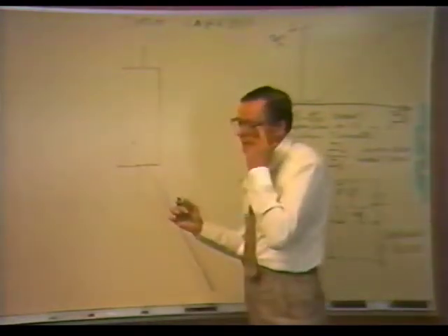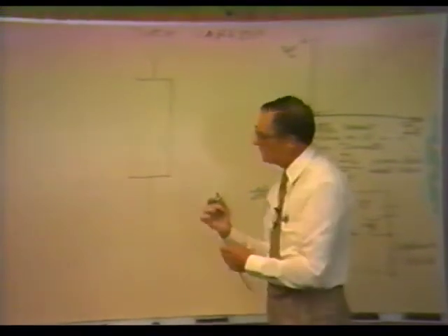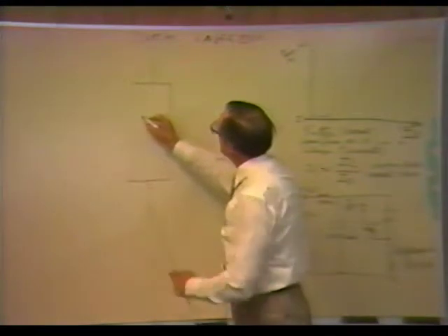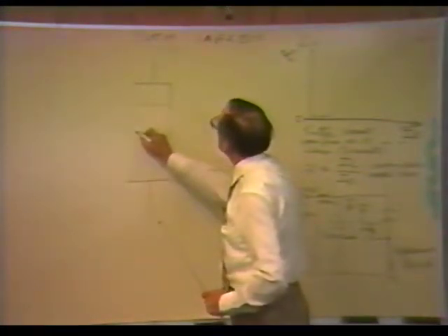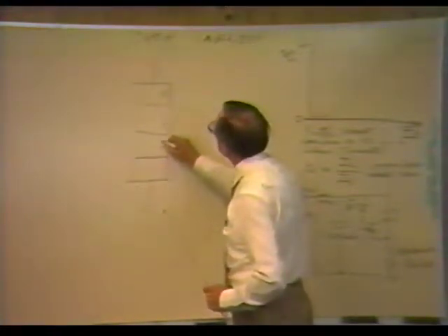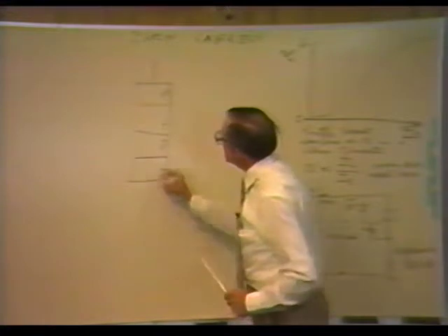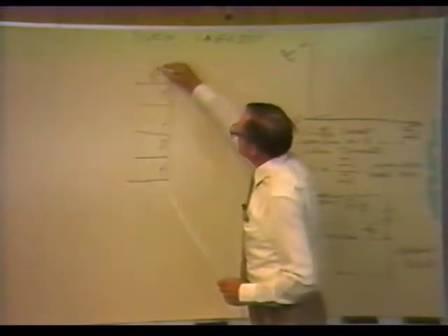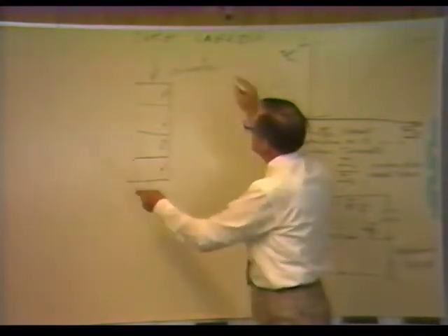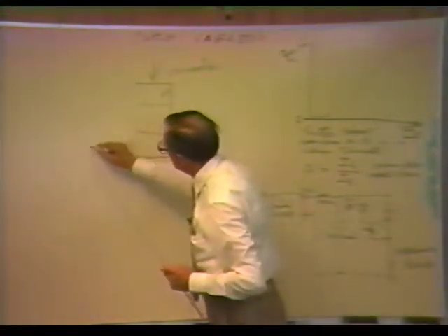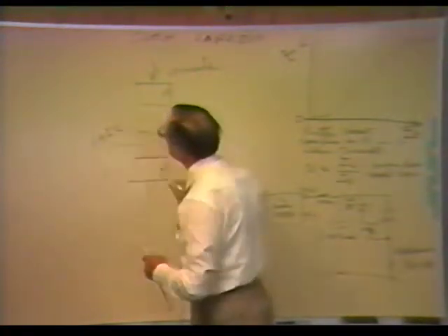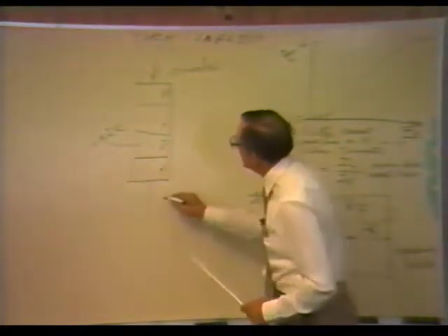Now, when they transferred the technology over, they used much of the same terminology that we used in the old hydrogen thyratron. In a three-junction, four-layer device, we have PN, PN. They called the anode, which was the plate before, the anode, just like we did in the old hydrogen thyratron. What we call the base in the transistor, they called the gate, which was the control grid or the gate of the old hydrogen thyratron.